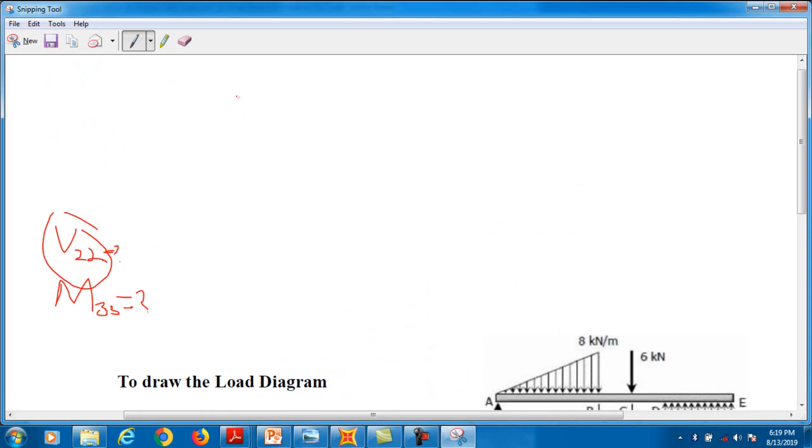basically you need to understand the axes. Okay, this is the global axis of SAP 2000. Clear? SAP basically denotes the x-axis with 1-1. Similarly, the z-axis is denoted with 2-2. Okay, and the y-axis is denoted by 3-3.